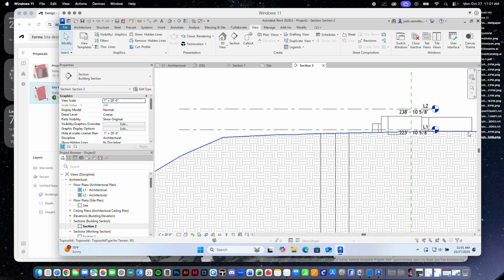We'll start to build this, and that's why I like building it just like you would build it physically, because as you start to go, everything begins to associate in nice, clean ways. So if, for instance, the envelope is hung off the steel frame, because you did steel frame first, the floors are derivative levels, right, then everything just sort of works. You don't break things as you start to manipulate. You start to learn more information.